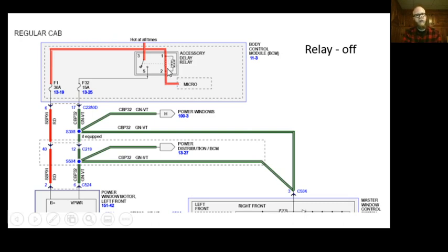No voltage is dropped across this relay coil because no current's flowing. Think about Ohm's law. To solve for voltage, I needed to know resistance and current flow. Current flow is 0. So what's 0 times, let's call this 50 ohms, 0 times 50, 0. So I have 0 voltage drop, so I would have available voltage right there.